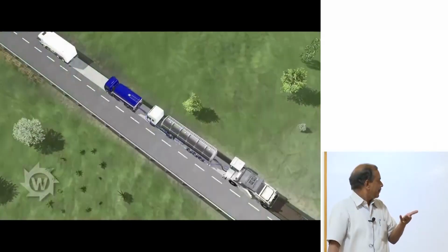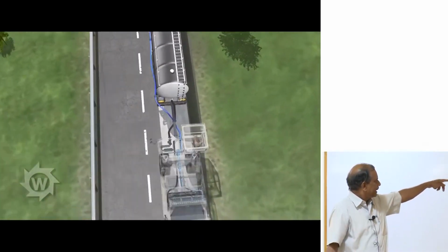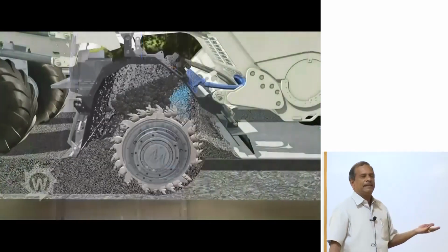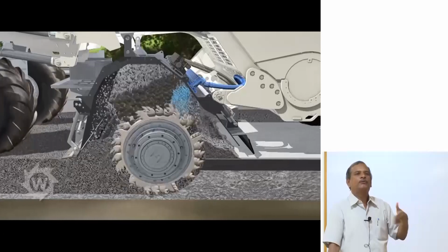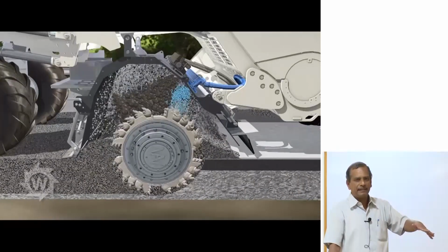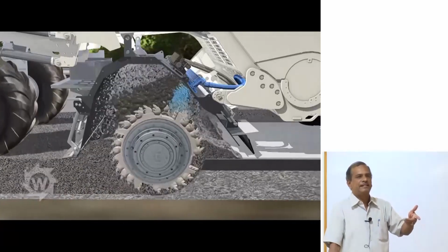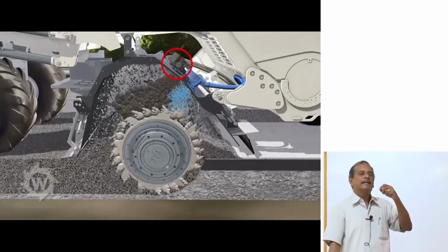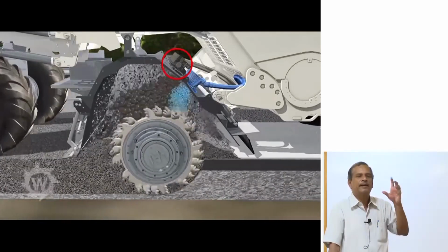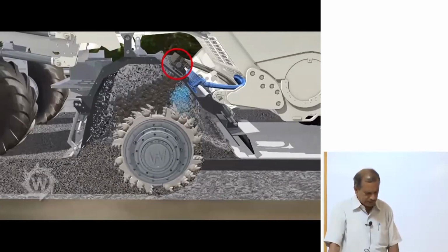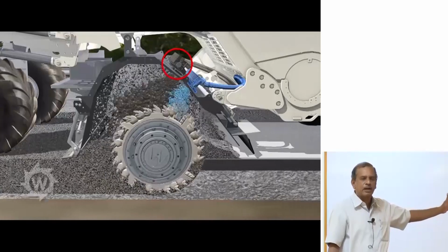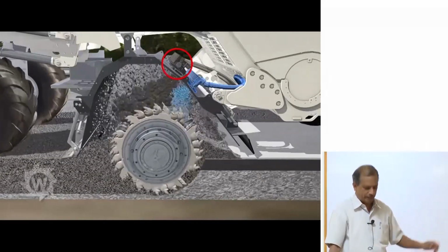I mill the material. I have a tanker of bitumen and a tanker of water. To the milled material, I use the foam bitumen, lay it and compact. So this will result in reuse of the material and stiffening of the aged materials. I try to rejuvenate the oxidized aged bitumen, and by the process, I can reduce the thickness of the bitumen layers. So this is one way of reusing the material, and this technology we have started adopting in several highway projects in the country today.